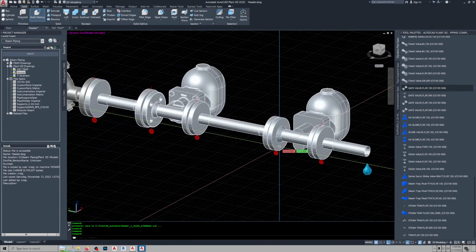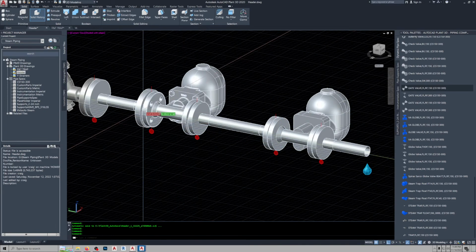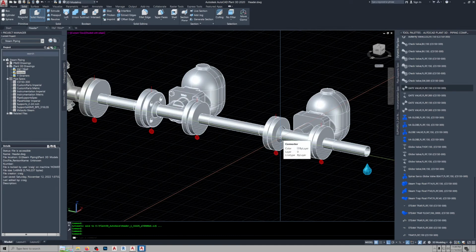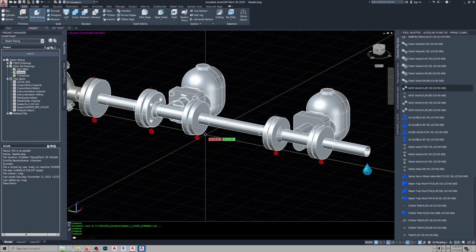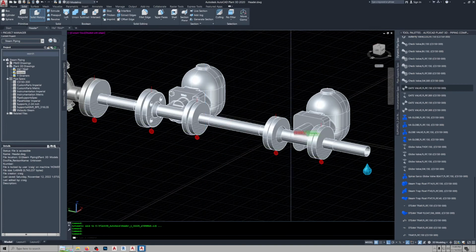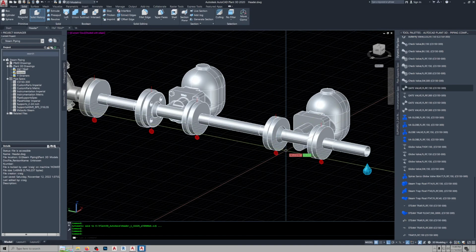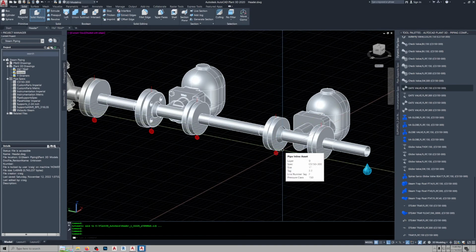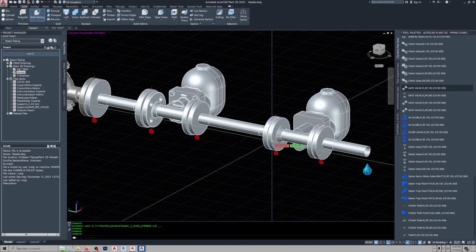Oh, the other thing was, you can see the flange sizes here because the parts on that Watson McDaniel site are 250-pound flanges. So when I created these extrusions, I made them for a 150-pound flange, which for a 1 inch was 4¼ inches. And that was really easy to do. There's all kinds of tutorials that'll show you how to do that stuff if you've never done it before.